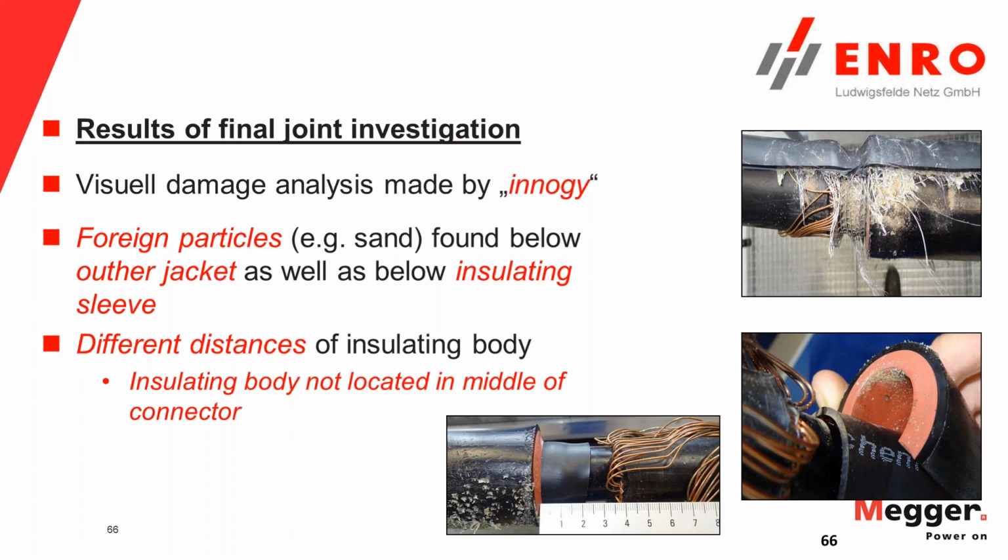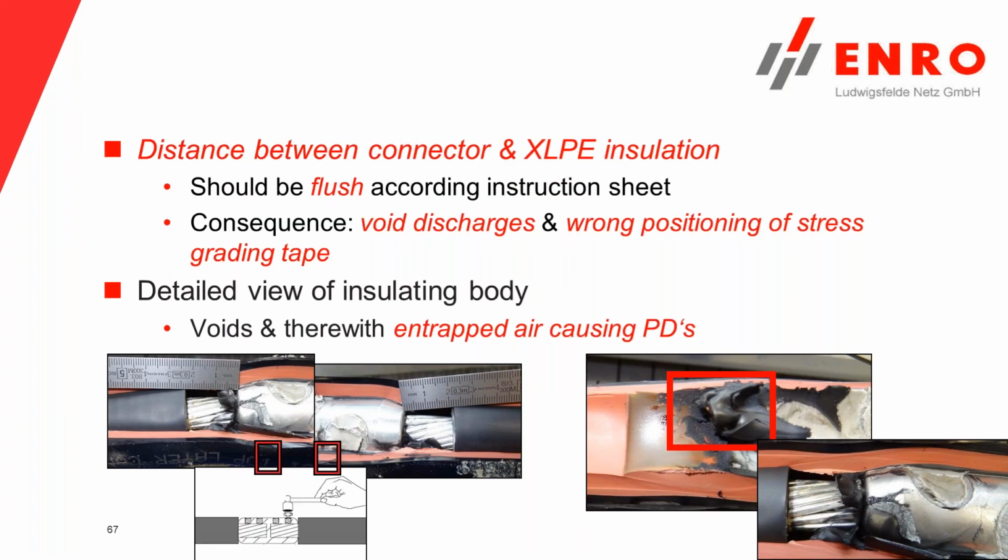I just wanted to show you the latest results. That is what I got back from our field test engineer that keeps track of that case. And he said, hey, look at this, they found this. So problems, definitely workmanship issues. And then they cut it open. So you see the analysis, and you see it should be a flush interface kind of, and you have voids all over the place, and an incorrect positioning of the stress cone or the stress element. And so you were entrapping a gas inside a void surrounded by solid material, and that caused partial discharges.